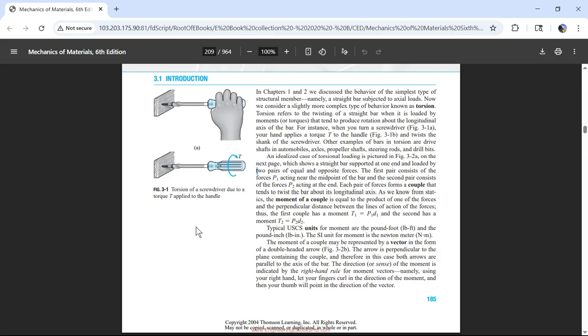Then you get 4 people, 2 on each side, pushing on that tank. Well, it's going to change in length by 10. It's going to shorten by a quantity of 10. And that's cool because springs are like that. They're linear. If you pull 1 pound on a spring, maybe it's going to lengthen an inch. Pull 2 pounds, that spring will lengthen 2 inches.